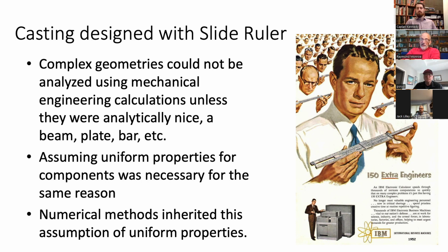I actually had to do a seminar for BAE Systems because they're upgrading the M88 tow truck for Abrams tanks. And that's a cast body. The people there today believe that it should have properties everywhere and be completely sound. And yet in the plate sections, the radiographic requirements are level 5, which is the poorest quality you can specify. Because it's the poorest quality you can specify, it means the designer was required to put something down, but he doesn't care. That's basically what it means.